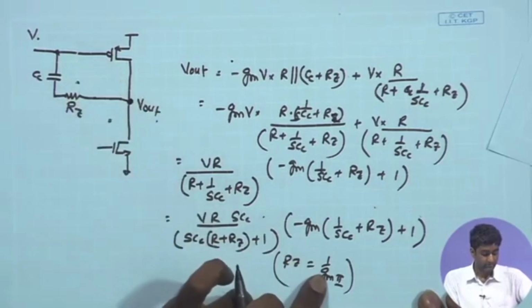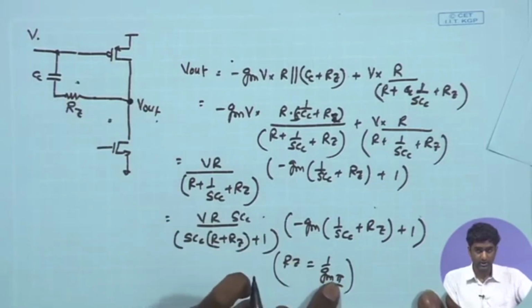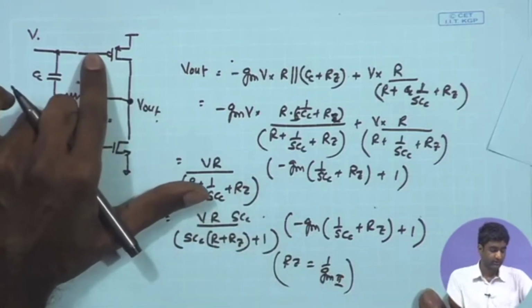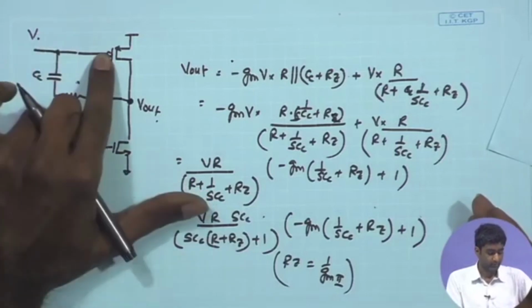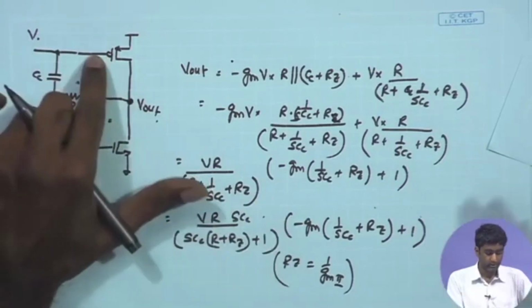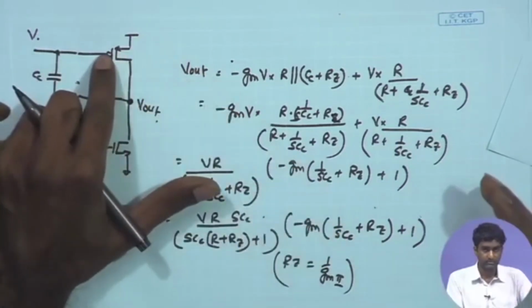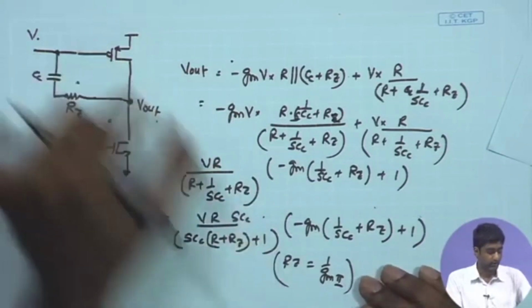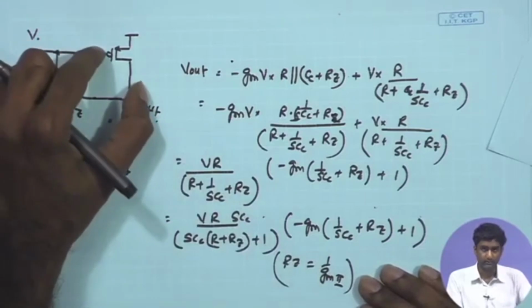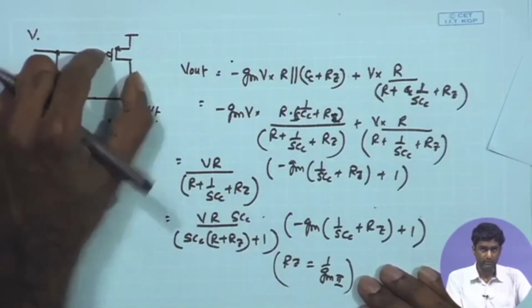You can have plus minus 50% or even 100% change in the Gm. If in simulation you set the value of Gm to be 10 to the power of minus 4, in the actual design you may get a value which is 2x or 50% of that. So, you can have a wide range in the values of Gm after fabrication.